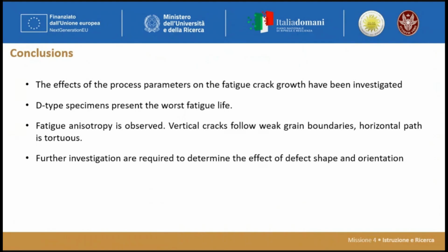In fact, if you remember, the curves of specimen D with the horizontal crack were worse than that with the vertical one. However, we have to further investigate the effect of the defect position and shape on the fatigue crack growth.